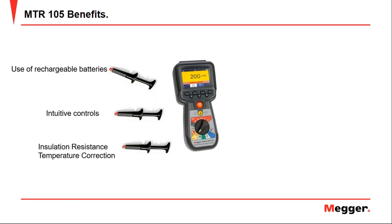Very important point: this equipment can perform the insulation resistance temperature correction, so you don't have to worry about it when you do the measurement. You are always going to have the correction of the value in the insulation resistance test. It operates up to 3,000 meters above sea level. It is very light and portable.